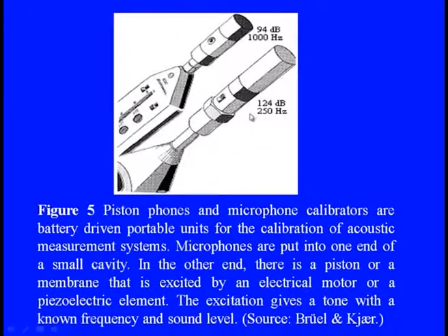Say, in the first case, if it is 120 dB or 250 hertz when we apply it, and we calibrate using a sound level meter reading of 124 dB, or if we measure the frequency of 250 hertz, this is absolutely okay. If it is not, then we need to check what other features we can use to calibrate. So, one is the standard or known value, and then we calibrate, check the output, and check the error.